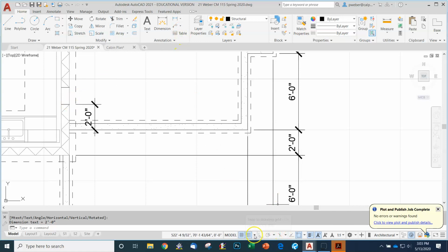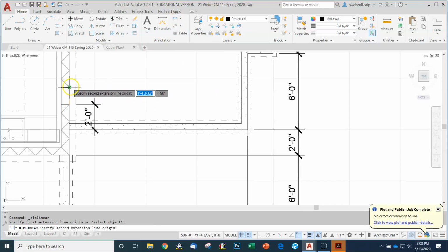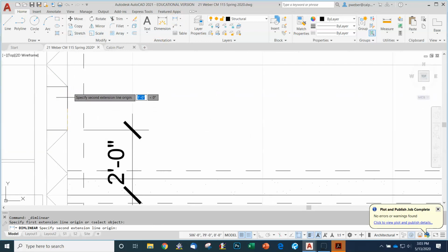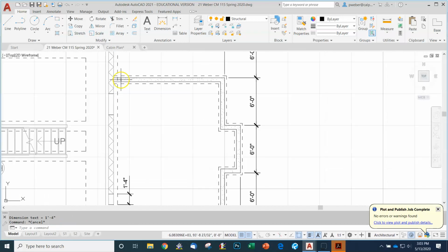So I think that, don't turn on, well, I guess we could keep that on. This could work out. Let's try this. I'll call it the dimension command, and OSNAP found that. OSNAP did find this. It's struggling, but it should read 1 foot 4 inches, perfect. Yeah, because what's happened is Snap and OSNAP are kind of fighting each other, but I kind of made it win anyway.